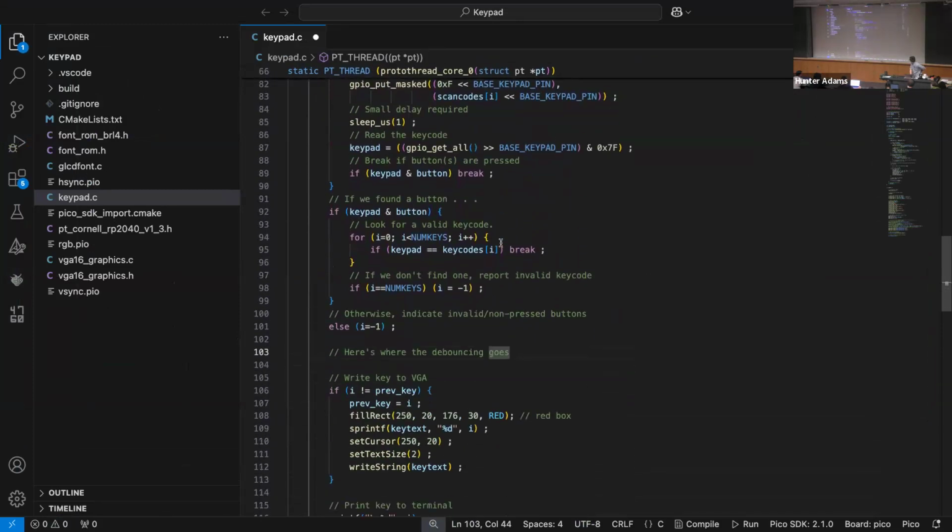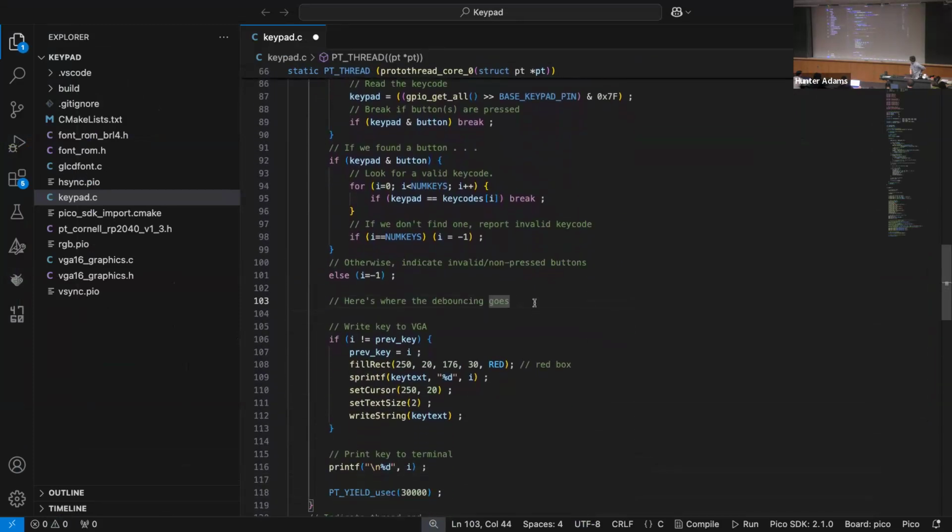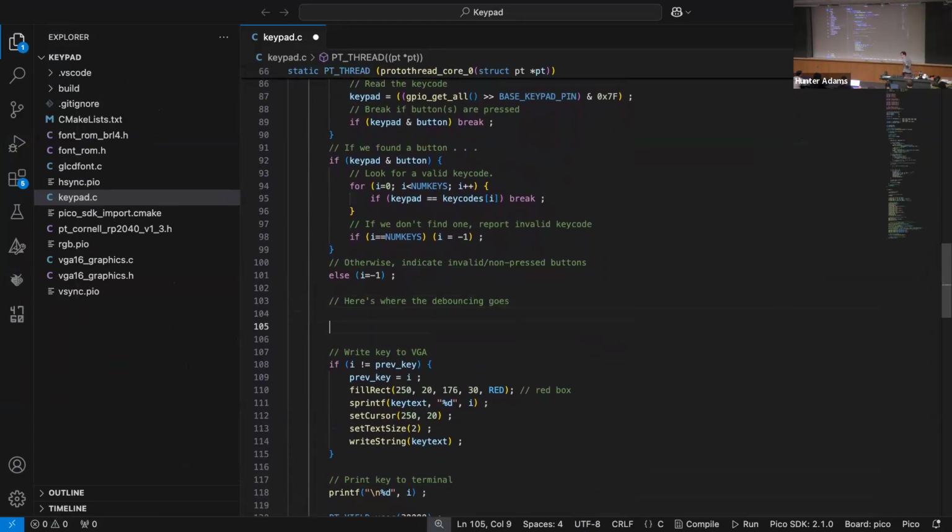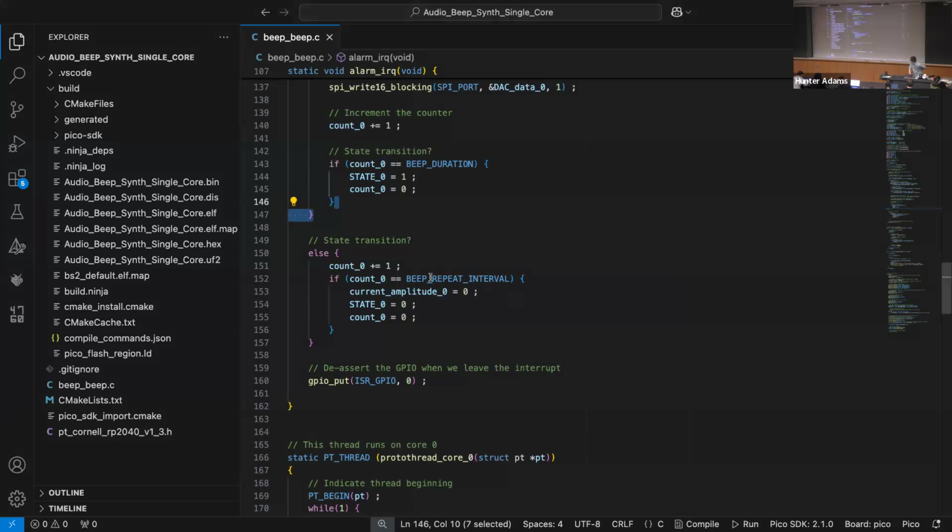we will have integrated this keypad scanner. Like I said, underneath the keypad scan, you will have the debouncing state machine that I just described. In the part of that state machine where you transition from your maybe pressed state to your pressed state, you include these 3 lines of code.